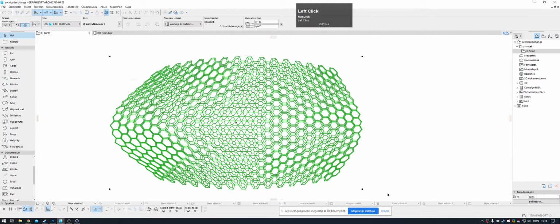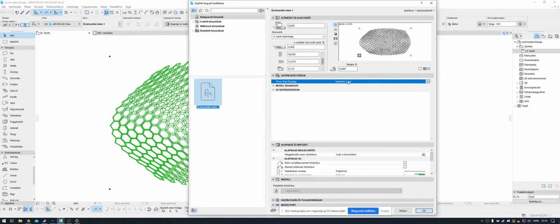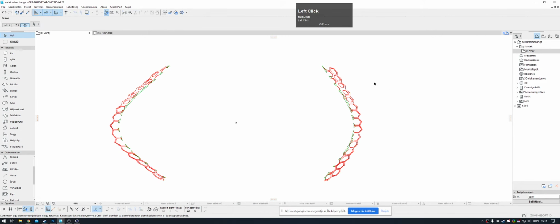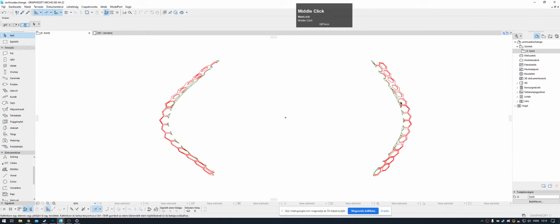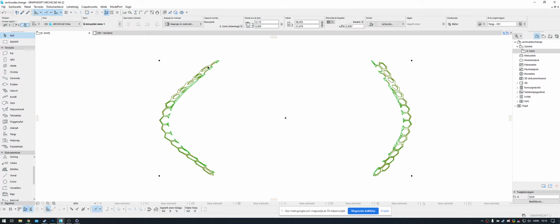It's on the default layer, and I jump into the settings, and I set the symbolic view to projected view, so I will see the floor plan of it with the section lines, which is good, because if it's, let's say, a pavilion, or I know what is it, under the shell, it would be really embarrassing to always turn it off and on and guess where the cut lines are.